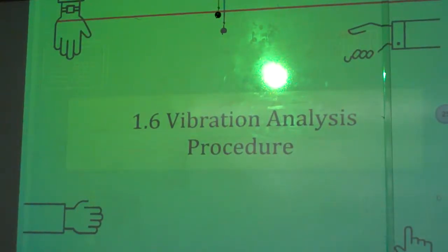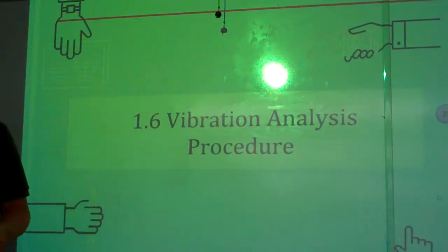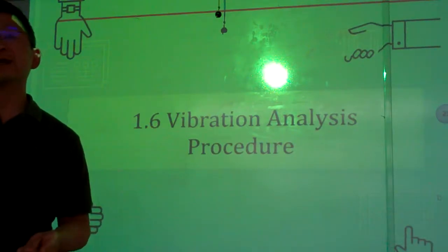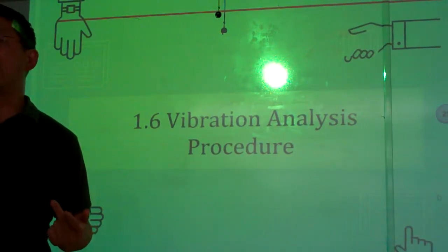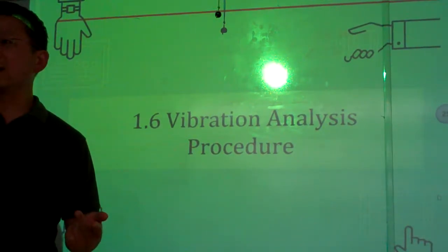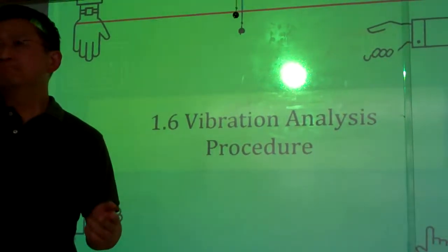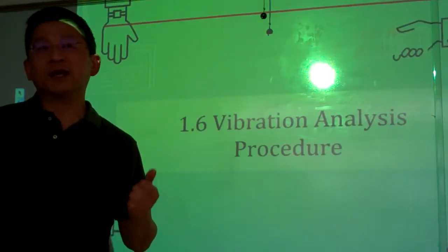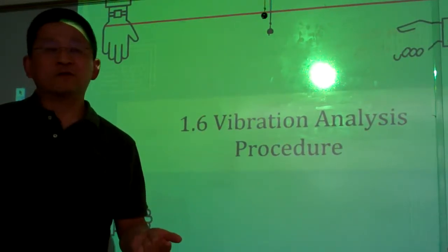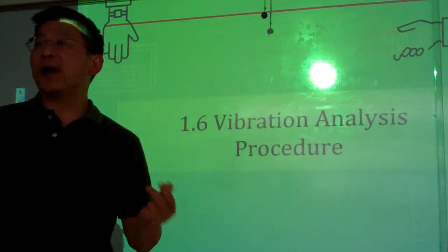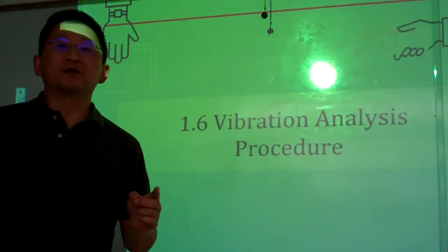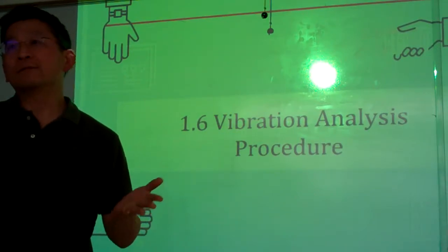Okay, so we're going to study our vibration system. It's a linear and discrete system, which means a finite number of masses, and it's deterministic. The function is given as a time function. It can be constant, or periodic like harmonic motion, or a combination of harmonic motions, or it can be arbitrary, like the step input. If you have taken control, then you should know the step input, like this one.